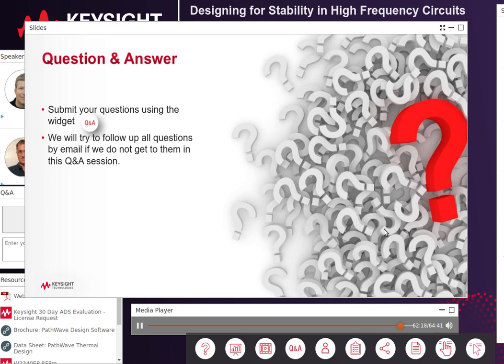If you're designing an IC where you cannot access internal breakpoints, is there any good way to understand areas of marginal stability? Yeah, I assume you're talking about in the lab, which is of course a big challenge, and it speaks to why you need to consider stability in the design process, where you can actually get to points that you couldn't otherwise get to in the lab.